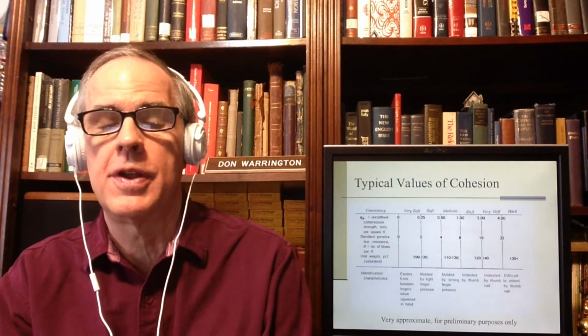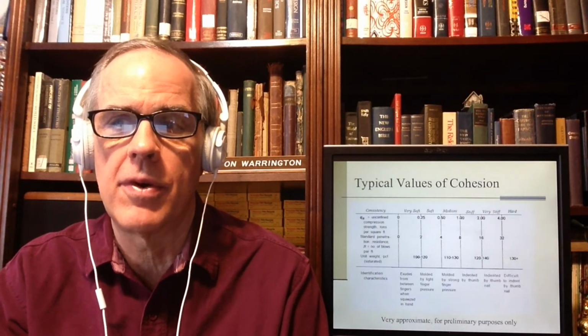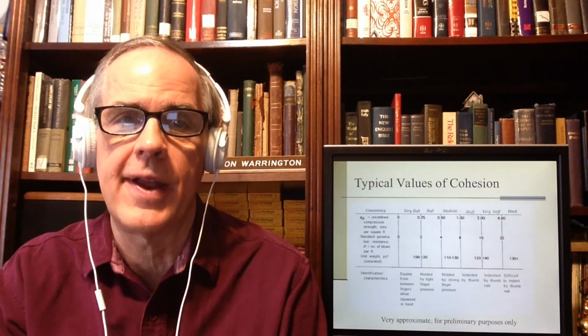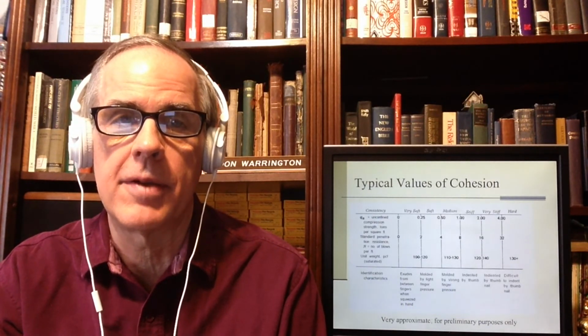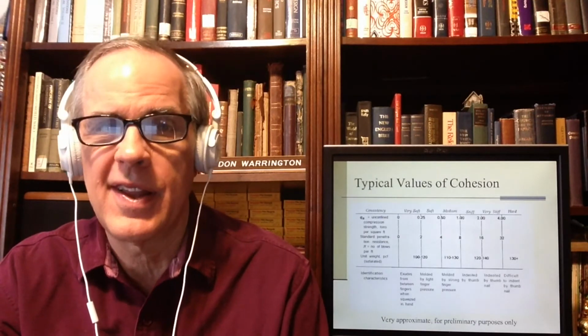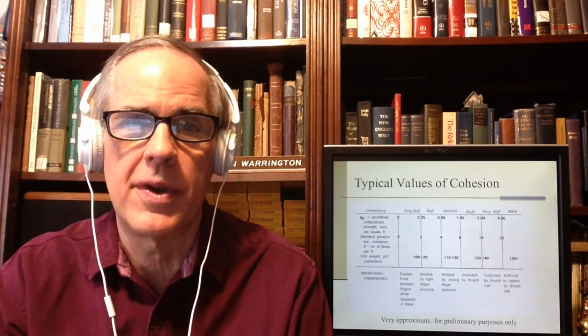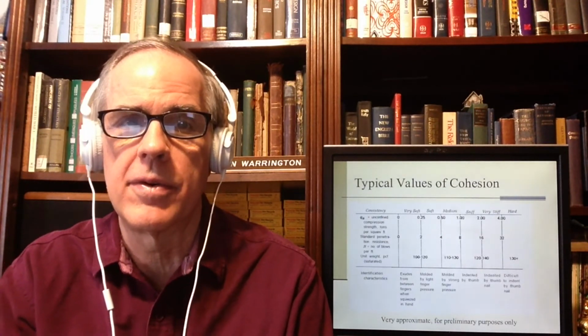For cohesion, it's more of a crapshoot, really, for cohesive soil. For preliminary purposes, they still have to be used with care. You would not really want to hang your hat on this. These can vary wildly depending upon the nature of the clay and whether it's moist or saturated or whatever. So you have to be careful using these.